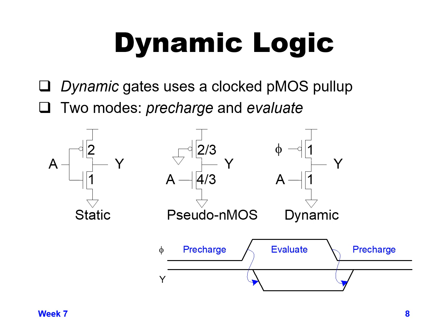And so the circuits below show, for an input inverter, the A goes to the PMOS device and the NMOS device. We have a value of 3 load on our input A. For a pseudo NMOS, we might use a little bit of a different ratio, so we have our value of A is 4/3 and the PMOS is 2/3, so that we can make sure the NMOS is able to pull the output low enough, even with the PMOS fighting it. We need to make it a little bit stronger.